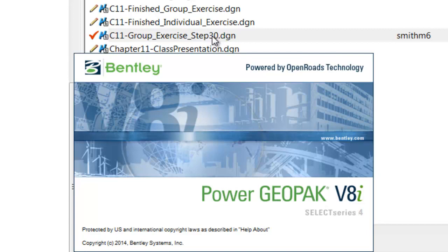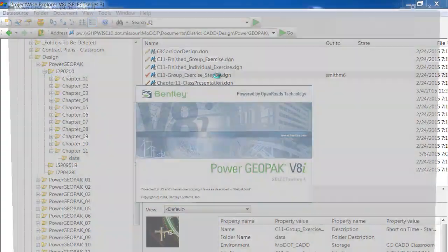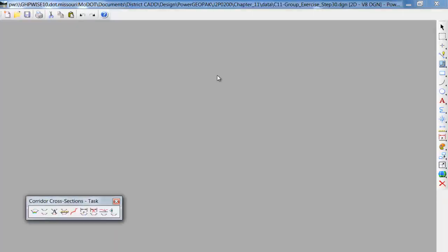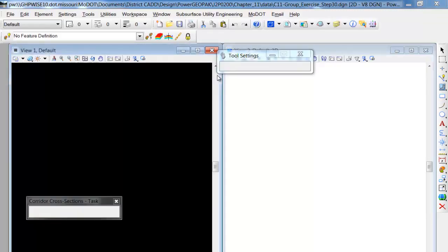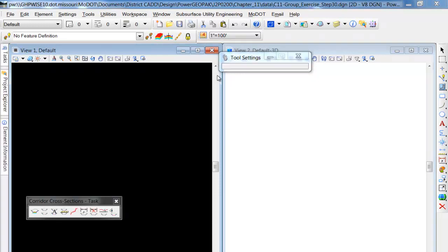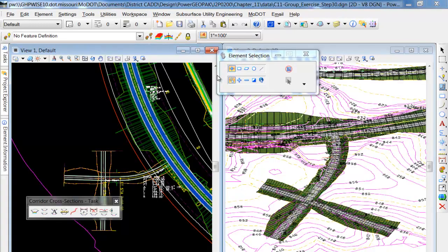Throughout this chapter, if you look at the exercise, it actually starts on 11-15. What we're doing throughout there is opening that other drawing. We're creating a GPK for job number 111, which we already have created for us. There's another portion in there, in step number 4, that talks about checking your geographic coordinate system. So if you haven't set the coordinate system or you don't know what the coordinate system is for a particular file, these are the steps you can go through to check to see if it has a coordinate system.